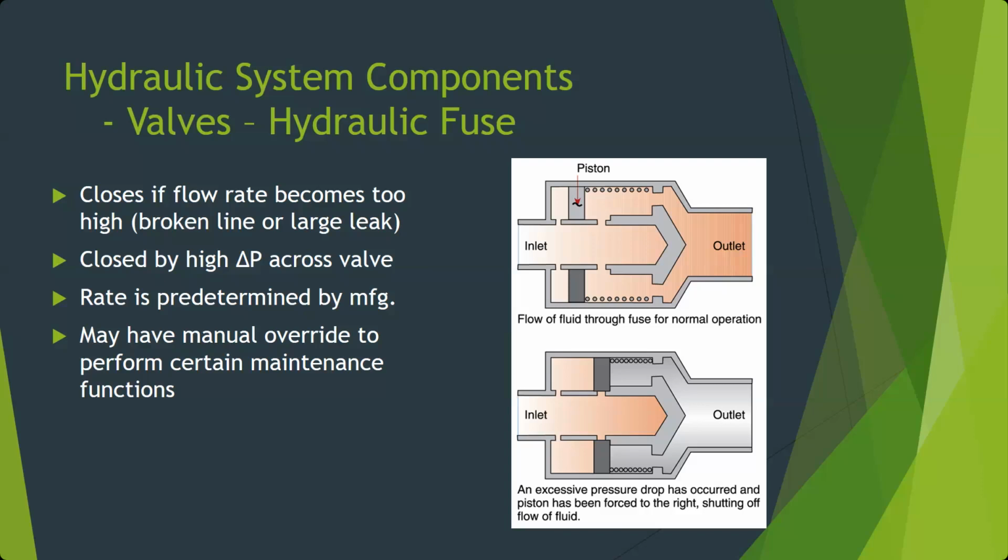A leak caused by outside influence, outside forces. What's that? Threads? Well, if you've installed it right, it shouldn't leak, and you should leak check it after. Someone said landing gear, but then said well. Where else on the landing gear? Where specifically on a landing gear do we send hydraulic fluid that is really close to FOD on the ground? What? The brake lines. Okay, that's the biggest area you'll see these.